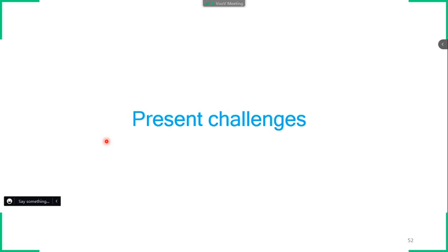Yeah, but for the first layer, that you can predict. For laying the next layers, you can predict it too. But for the first layer, you have to be concerned about the dilution. That is what my point is. For second layers and so on, you need not worry about too much dilution; too much dilution is undesirable for subsequent layers. But for the first layer, it should be well diluted so that it can anchor with the substrate. Okay, so that is what you are understanding.